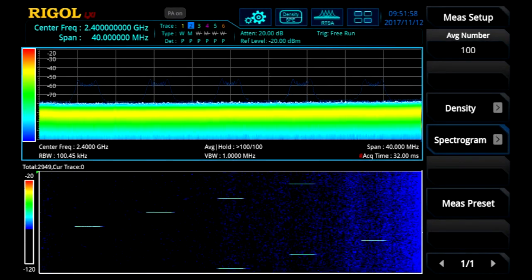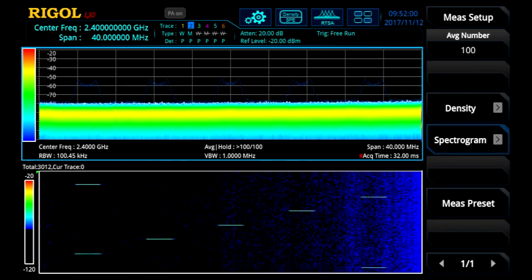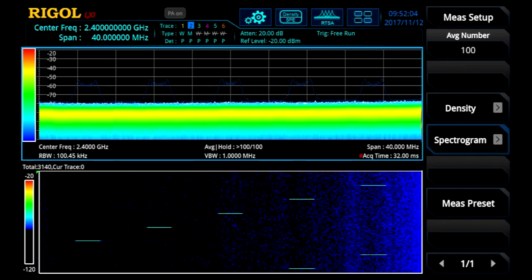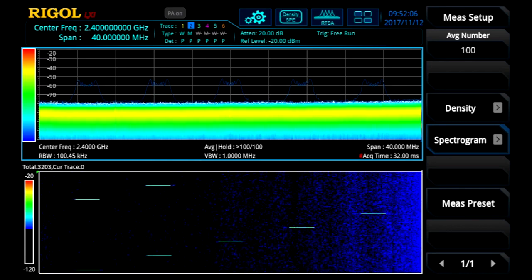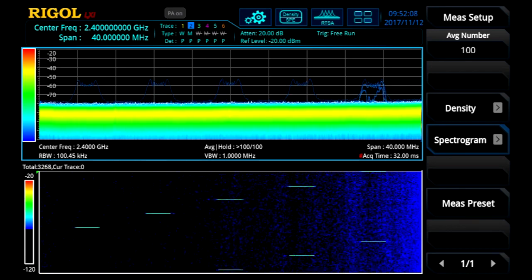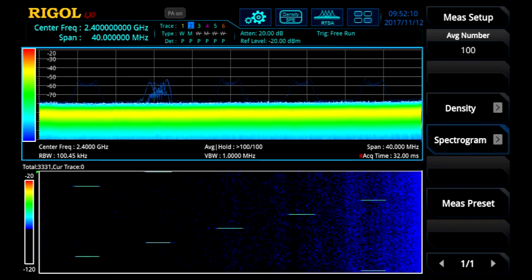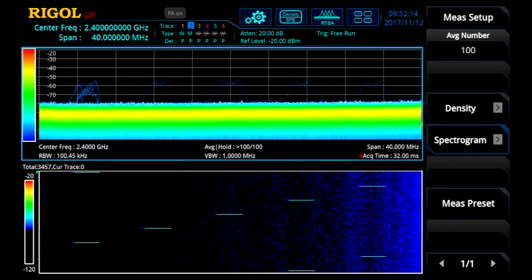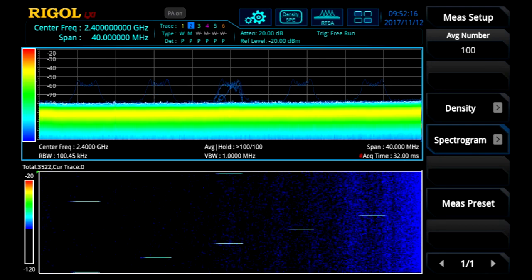First, real-time analyzers enable engineers to find more transient signals the first time they look. The RSA 5000 with 40 MHz of real-time bandwidth comes with 7.45 microsecond, 100% POI, or probability of intercept. Any event lasting longer than this is guaranteed to be captured every time it occurs.